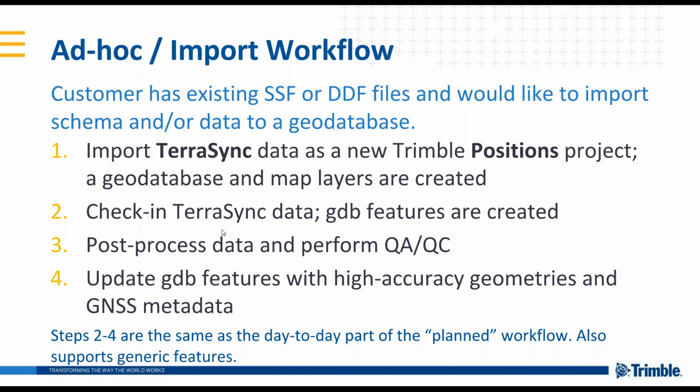Optionally, I want to be able to get that schema in such that I can maybe create a different type of project. I want to bring a schema in from an SSF or DDF and then use it for a TerraFlex project or use it for an ArcPad project. So the basic workflow here is there's a separate type of project you saw there, and I'll show you in a minute, called a TerraSync import project, and this is where you're able to create a new positions project by browsing to an SSF or DDF file.